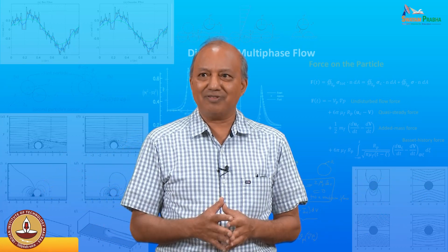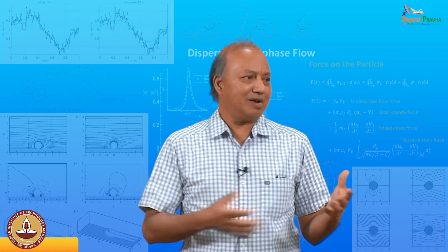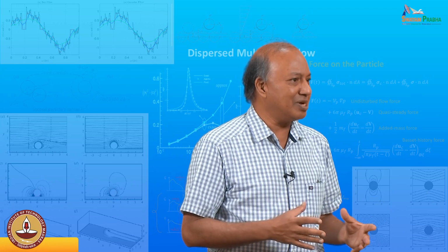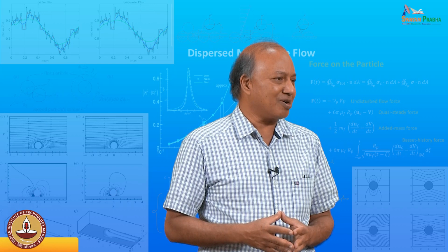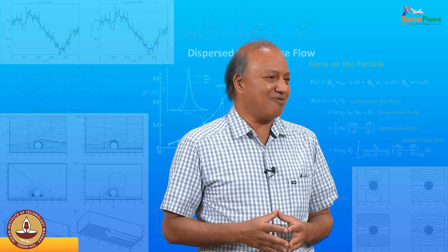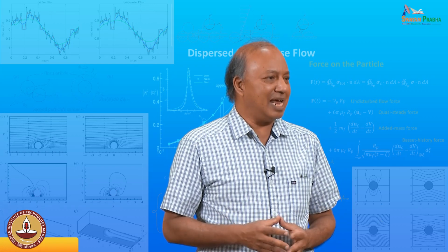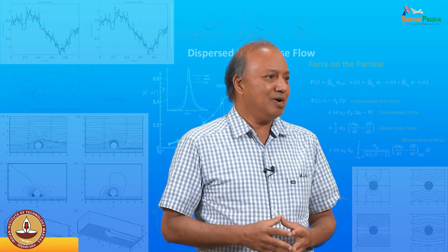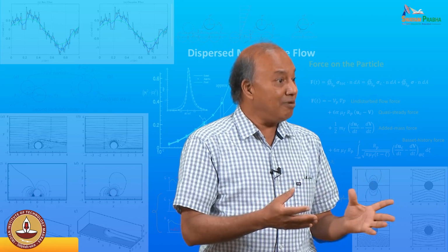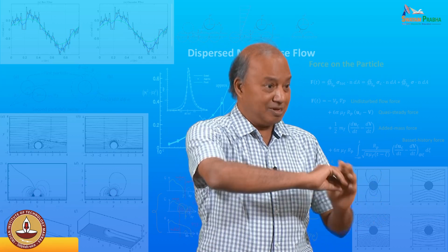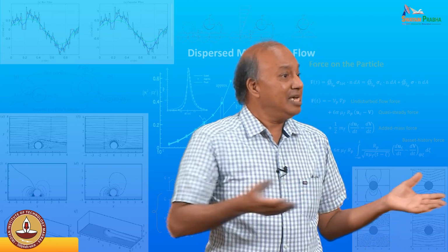I have not gotten to the final punchline of how to formulate the equations, but for the last 2 hours we are just laying the groundwork of why multi-phase flow will be challenging. The point I am trying to make is, we all know in LES, large eddy simulation, we erase all the subgrid turbulence, but now you want to think there may be structures, clusters happening within your grid, and that depends.